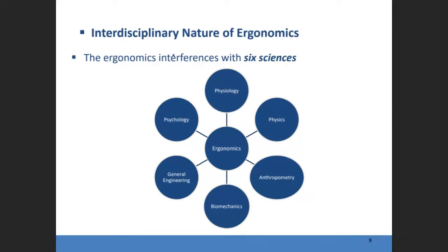Anthropometry, why do we need the science of measurements? When I design a chair, I consider an average height and the maximum height and the minimum height for male and female, both genders, who's going to drive the car, both genders. And the same within each gender, we have average height and also max and somehow minimum. How do I design it in a way that can fit this population? That's why I need anthropometry.